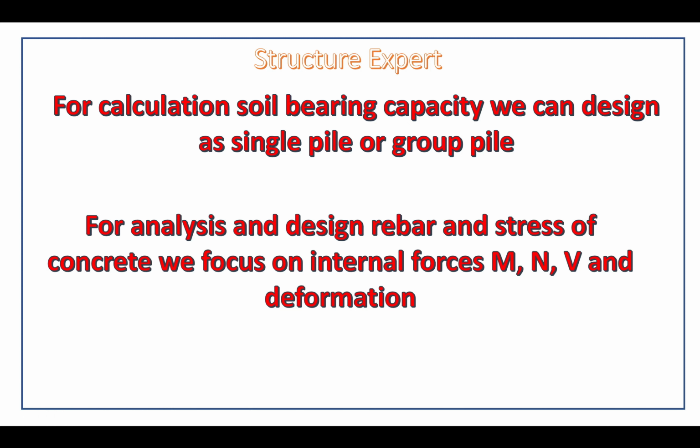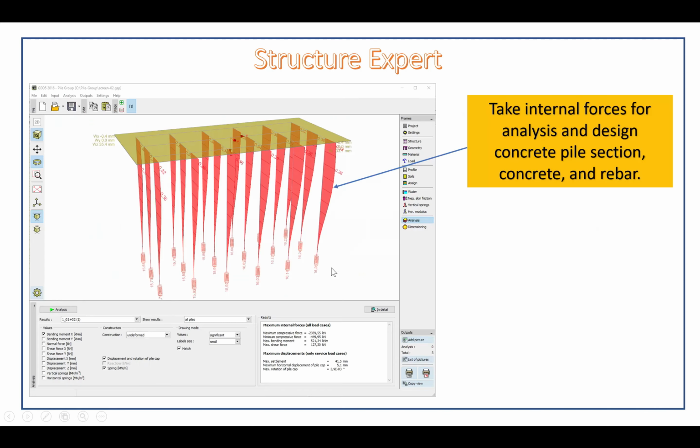After you apply the load, you will get the internal force, and we take the internal force to analyze. This is very important. We consider the moment, the shear force, and another one is deformation. It is a very important parameter for analysis and design in concrete bored pile.